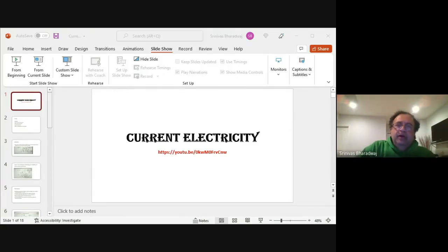Now, if you have a potential difference delta V and you have an I, therefore you end up with this. And sigma, as you know, is the conductivity. Conductivity is 1 over resistivity. So keep all this in mind. Now, the other idea is that not all elements completely follow Ohm's law. Some elements will not have linearity. Over a range they may be linear, but beyond a particular range the V versus I may deviate from linearity. Elements that show non-linearities, of course, are diodes and field effect transistors, FETs.